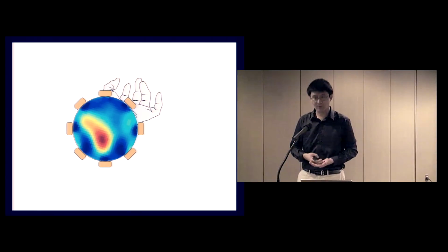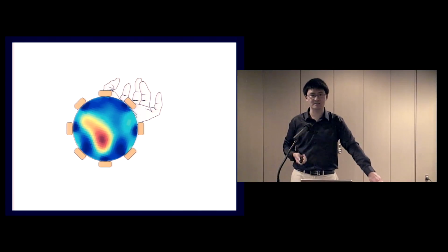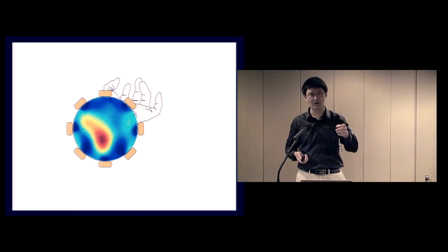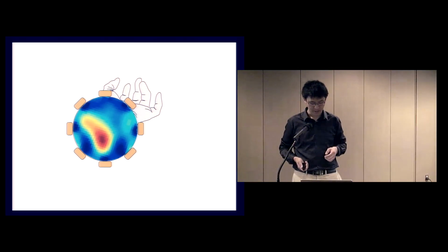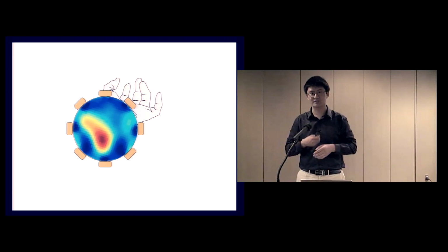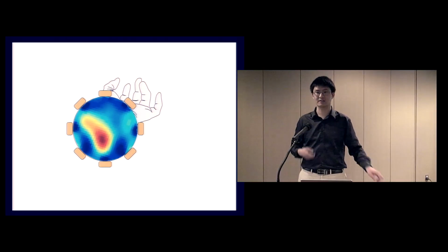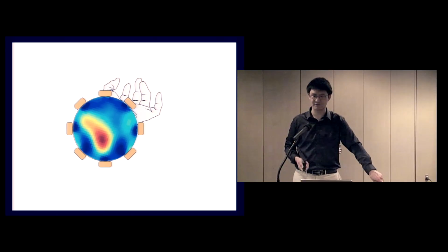Now, this two-pole sensing approach is conceptually very simple and simple to implement, but the major drawback is that it's very sensitive to the impedance at the electrode itself, because that electrode is also part of that electrical path that's being both generated and measured. If that electrode has a different impedance, for example, if it's not securely attached, or if the skin happens to be wet with sweat, then the measurements will change significantly, and that will adversely affect accuracy.